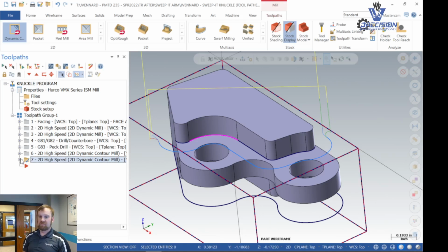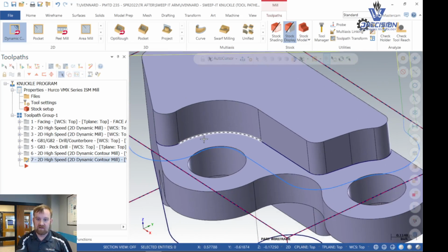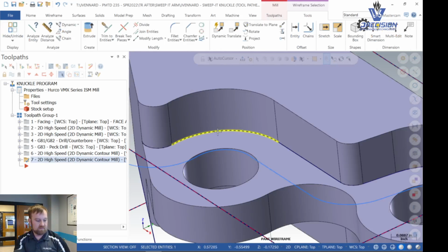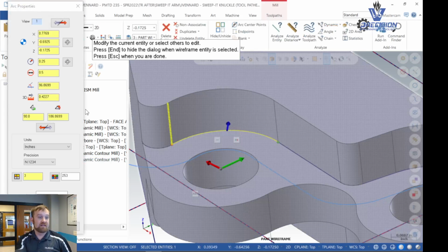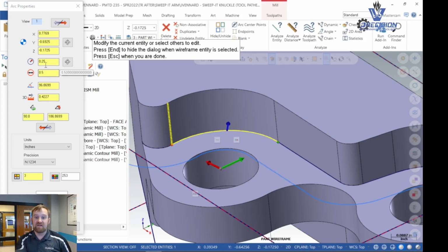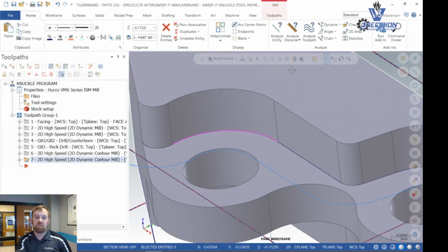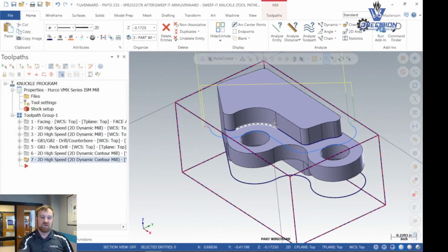I mean, we're literally taking 2.5 thou off most of the wall, and then even in that little corner there, there's not much left either. Like right here, as a matter of fact, that one actually is a 1/2 inch, so there's going to be very little extra material there. So nothing that's going to pull on the tool or anything. So just depending on how heavy the cut is.